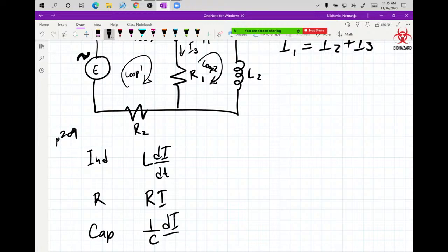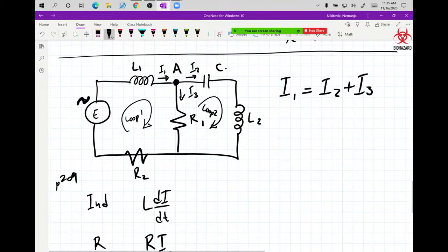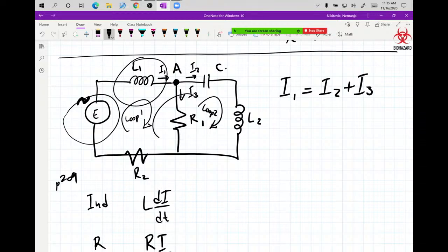Now, this tells me that I have a terrible circuit up there because it's squared, right? Because my capacitor should be here, but that's okay. So it's shared by both loops. Whatever. So now, the sum of all voltage drops needs to be 0 in the loop, right? So when I add the 4 components that you see in the loop, their sum needs to be 0. Now, E is making electricity, and the other 3 are spending electricity. You can think about it that way if that's easier, right?